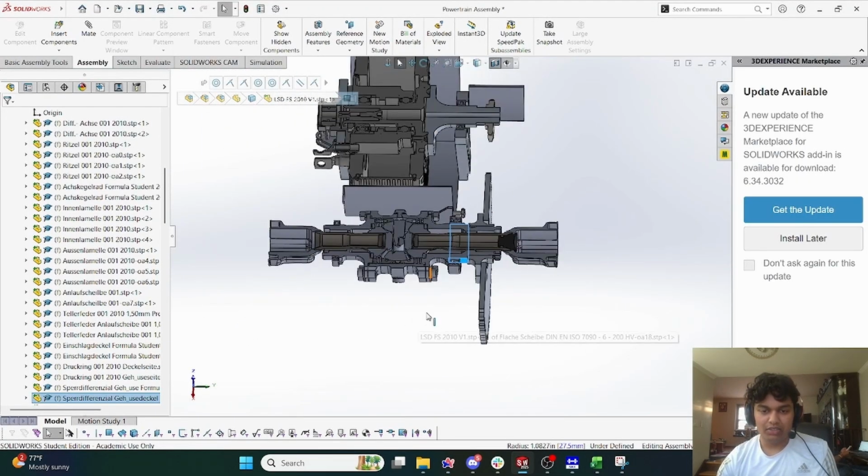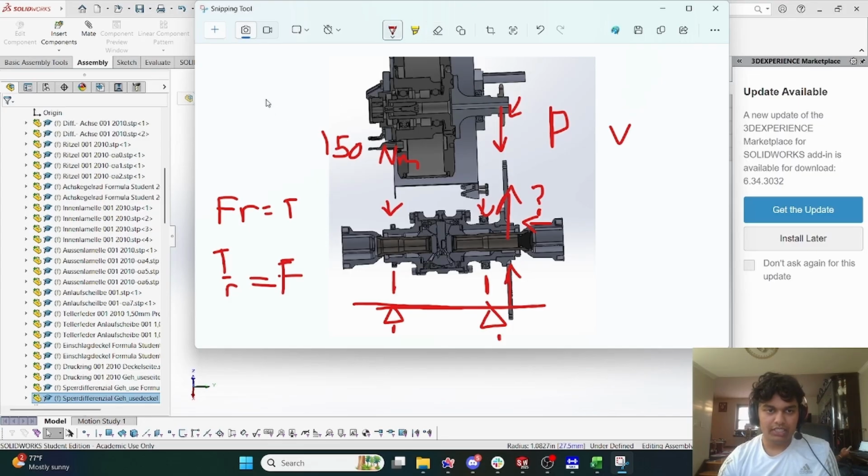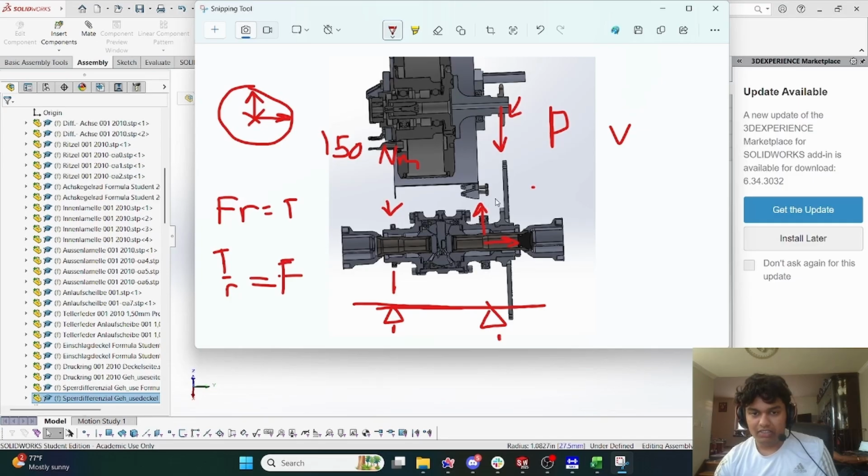Next, we talk about bearing type, and we use deep groove ball bearings because they're very good at handling radial load. What radial load is, if I clear some space over here: radial load is essentially stuff acting on here or acting on there. Meanwhile, if you had a load going into the page or out of the page, that would be considered axial load. So in this bearing over here, the radial loads would be like this, and axial loads would be like this. They're very good at handling heavy radial loads, which is what we experience. I mean, this experiences 1,500 pounds, so a lot of radial load.